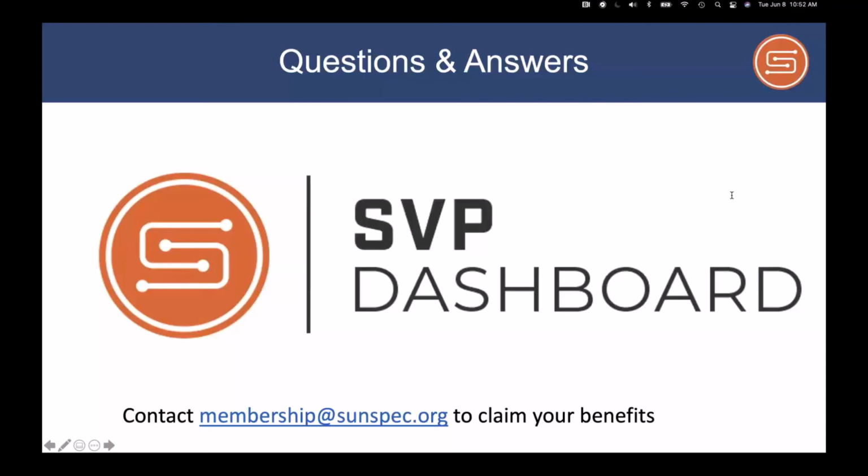Now I want to get back to answering a couple of these questions that came up on the chat. Pablo was asking, on the slide that showed the gateway, is the SunSpec Modbus server, or rather the client, and the DER the master? Well, the Modbus server in that particular case runs on the DER device, and the client actually is in the gateway.